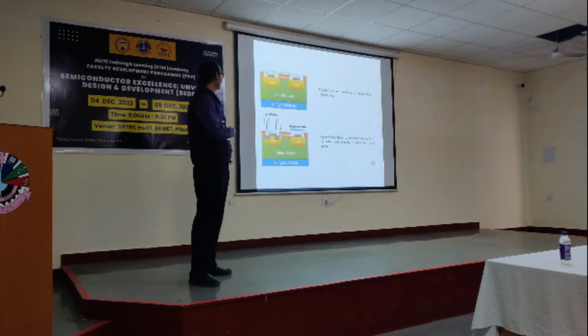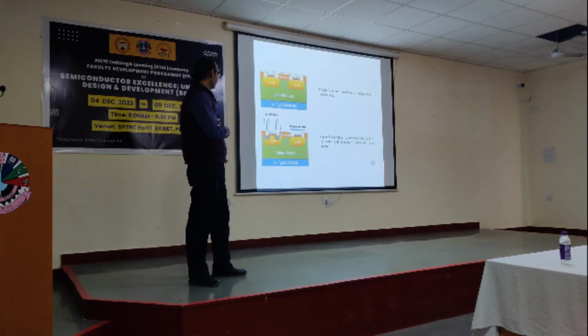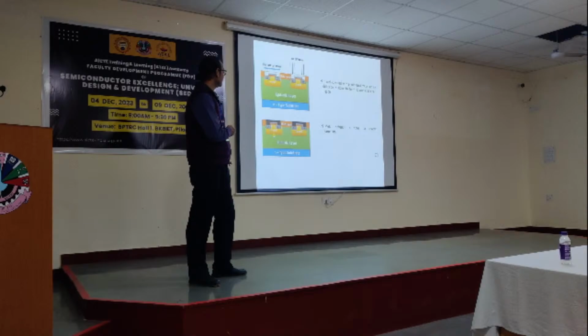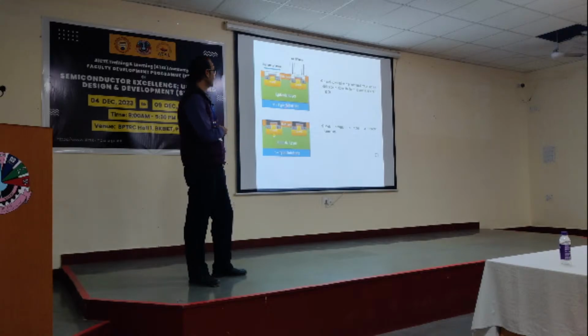So see, this is covered with photoresist. I will implant source and drains for a PMOS. Okay, similarly, then we will cover this side. We will implant source and drain, that is N plus, for the NMOS on P well.